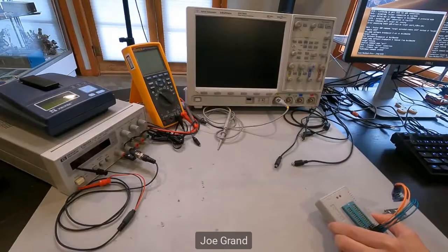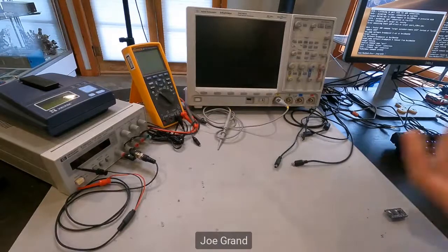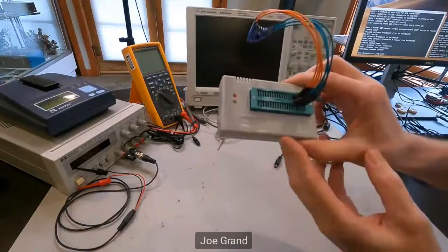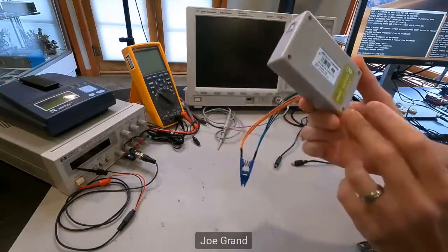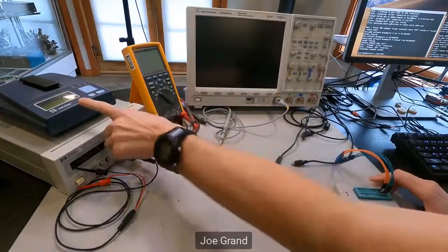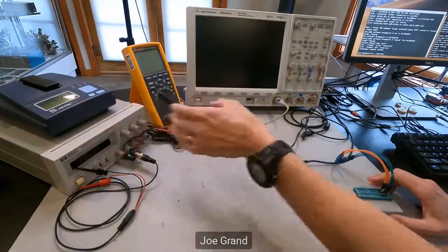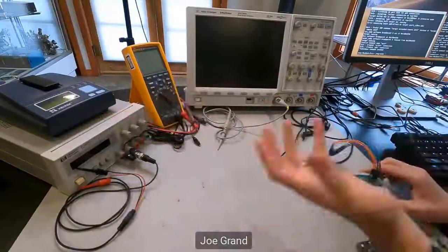And here, I'll switch to the slide also, which is our next party trick, extracting memory contents. There are a lot of different methods to extract memory contents. Again, there are open source tools. So I'm using a TL866 2+. You can get them on eBay and AliExpress and some other places for about $50 or so. I also have a Xeltek 501S, which is more of an engineering, not necessarily production model, but more of a high-end device programmer. These will support 100,000 different types of devices or something like that.